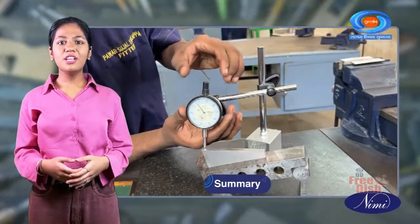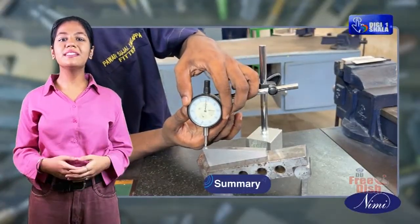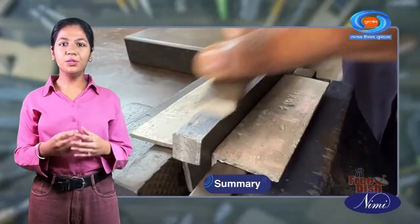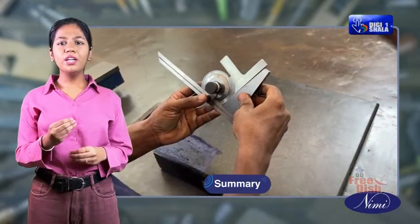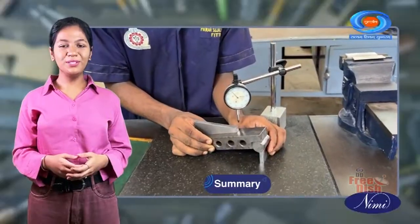The angle is adjusted by using shims or other means to achieve the desired angle on the workpiece. The scraping process is carried out using a scraper tool, applying even pressure and making controlled strokes. The angle is periodically checked using a precision level or an angle measurement tool.